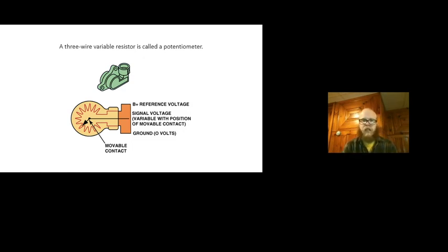So it's pretty important that we have that clean voltage, so that we know the voltage coming through this wire means exactly this. It's exactly at 33% throttle angle, right? I don't want it to be somewhere between 20% and 45%, or somewhere in that range. The vehicle's not going to run very well if we don't have these exact values.